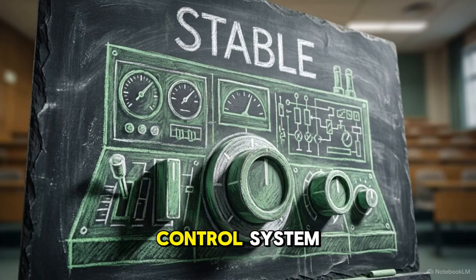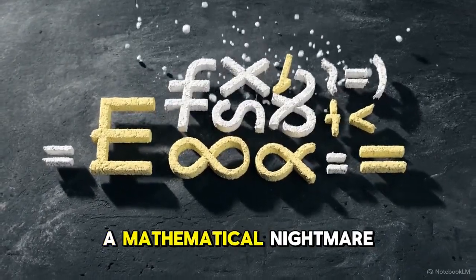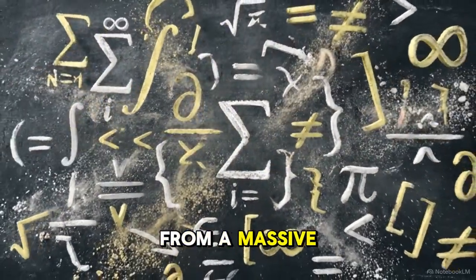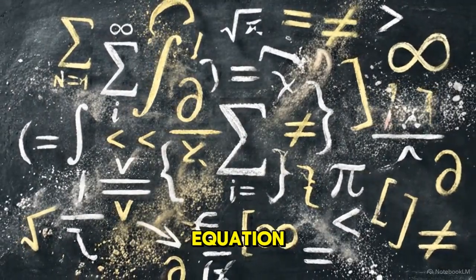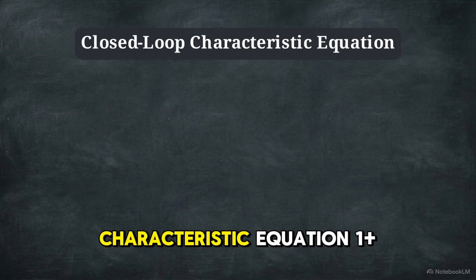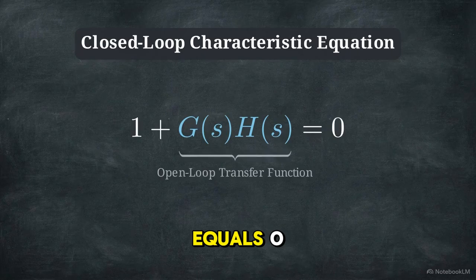When designing a control system, knowing whether it will remain stable is paramount, but finding that out often leads to a mathematical nightmare, trying to extract the exact roots from a massive, high-order polynomial equation. This foundational math is known as the closed-loop characteristic equation, 1 plus the open-loop transfer function, G(s) times H(s) equals 0.